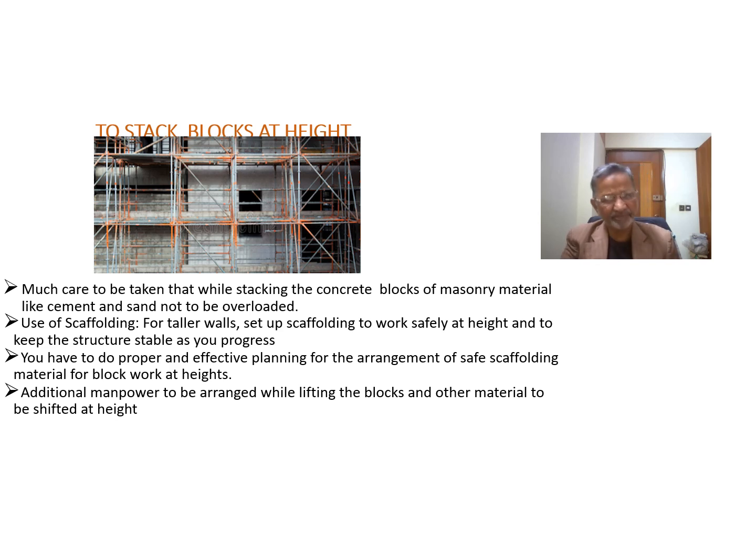The mortar is to be shifted through the hoist, not through the manpower. So all these cares are to be taken while working at height by the masons or the workers to do the masonry.